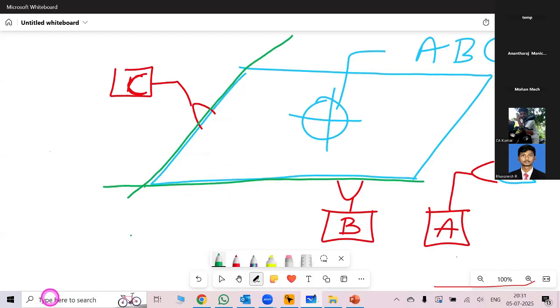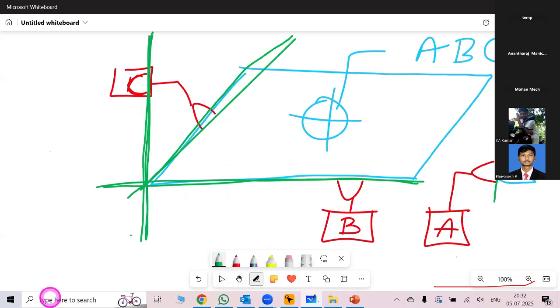At the point of intersection, you can create one plane. This plane is perpendicular to B and it is perpendicular to A. So on the drawing, this is not perpendicular, but on the fixture, you can make it perpendicular. So this will become your reference. From here, how far is the hole? That can be made or measured.